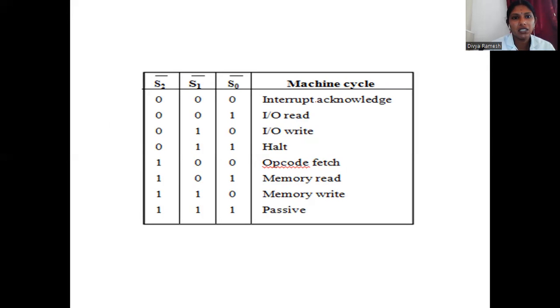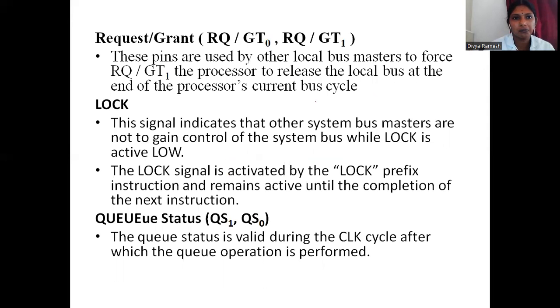Depending upon these status signals S0, S1, S2, the operations can be selected, whether it is a read operation or write operation, whether the opcode has to be fetched, or memory read or memory write. It depends upon these three status signals S0, S1, and S2.